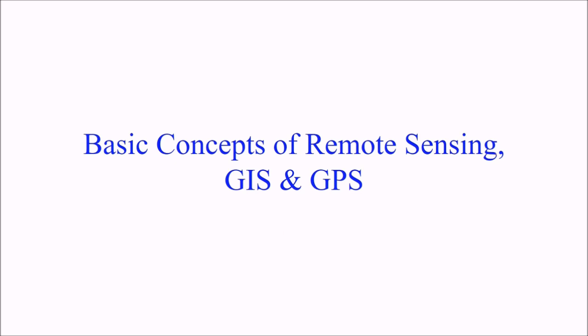So this data which is remotely sensed is not at that position. You have to bring it to that level after geometrically correcting it, after a lot of corrections such as atmospheric correction, etc. Then it is spatially referenced. Just clicking through a camera, that camera image has no spatial reference. That means if you place it on a globe, it is not going to be placed anywhere.